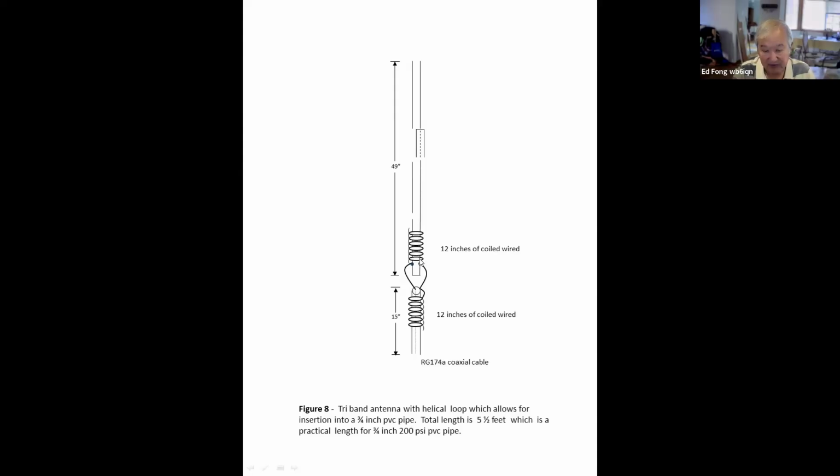If you make these coils really, really wide, in the extreme, it's a dipole and it works. But how much can you coil this? If you coil it 3 turns, the coils are pretty big, but then it's horizontally polarized. It will work, because it's horizontal. If you make it too tight, then that center null you're emulating isn't perfected. So we found that about 6 turns, which makes it about 3/4 inch, 6 turns each way, will resonate. That's amazing. It will actually resonate, and you can tune it.